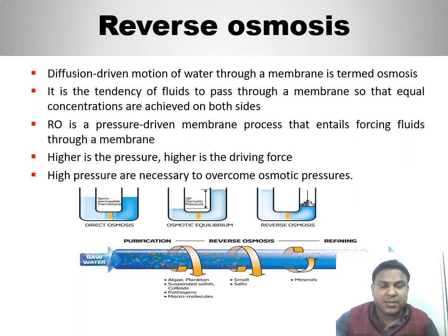Reverse osmosis is the major separation process categorized under the pressure driven membrane separation processes. You might have heard about osmosis. Osmosis is simply diffusion driven motion of water through a membrane. In osmosis, water molecules move across a semi-permeable membrane from a higher concentration liquid to a lower one, which requires no extra energy expenditure nor any external process. In RO, if we consider especially water,